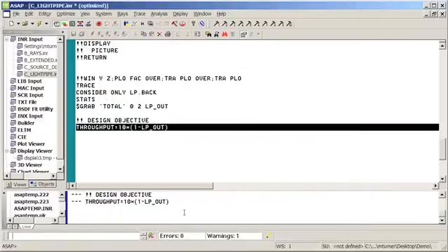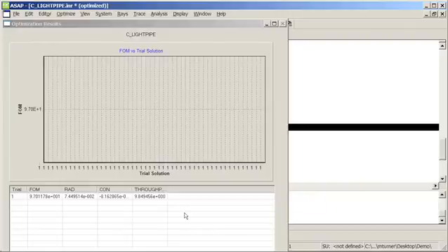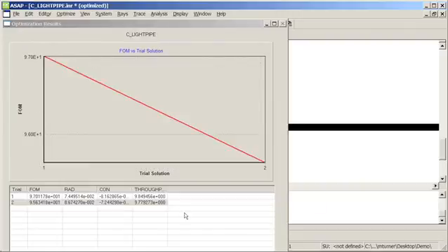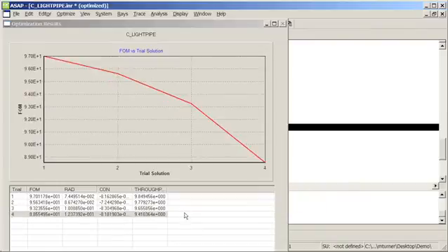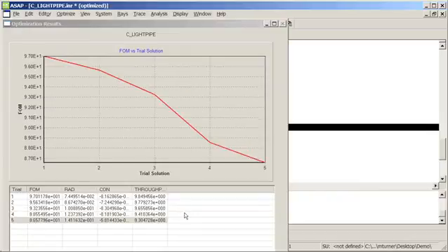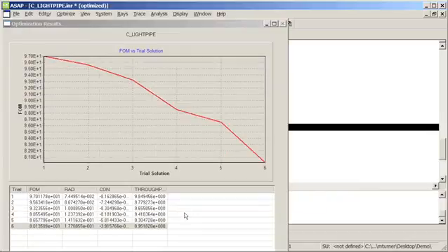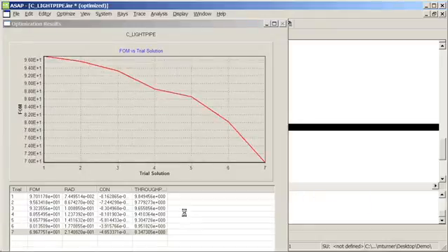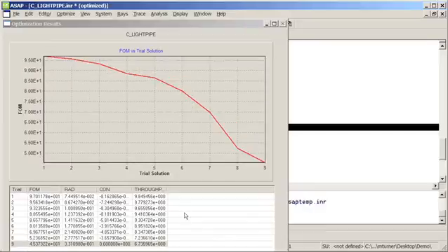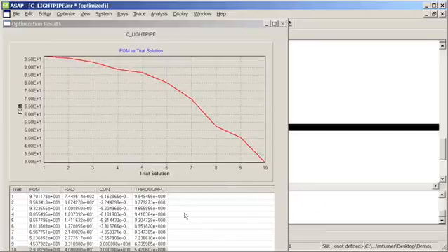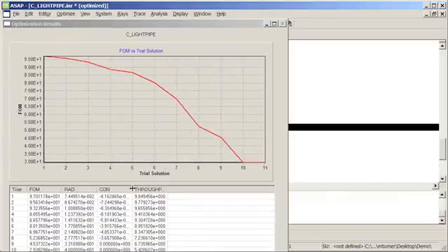What you'll notice with the simulated annealing is initially ASAP will take broad swings in the merit functions of the different trial solutions. The hotter the temperature, if you will, the more likely ASAP is to select or accept a solution that results in a significantly degraded merit function. As the temperature gets lower and lower, ASAP becomes less willing to accept those solutions, and then finally, towards the end, only trial solutions that result in an improved merit function will be accepted. And as you can see, the optimizer seems to be reaching into a reasonable level of solution space quite rapidly.